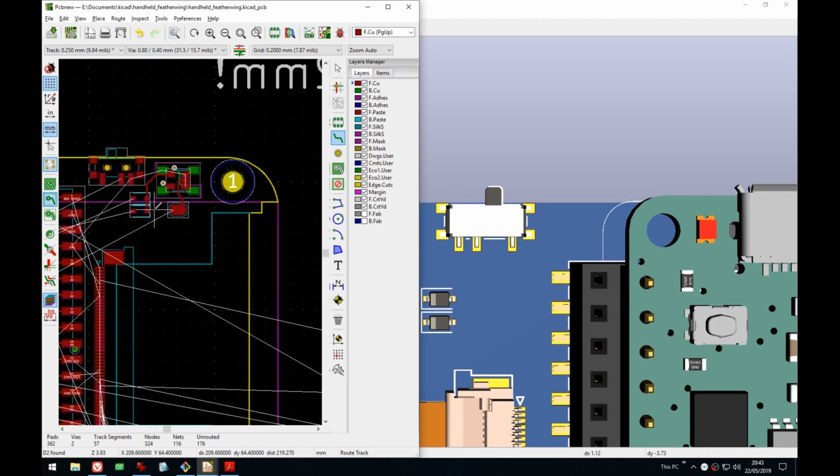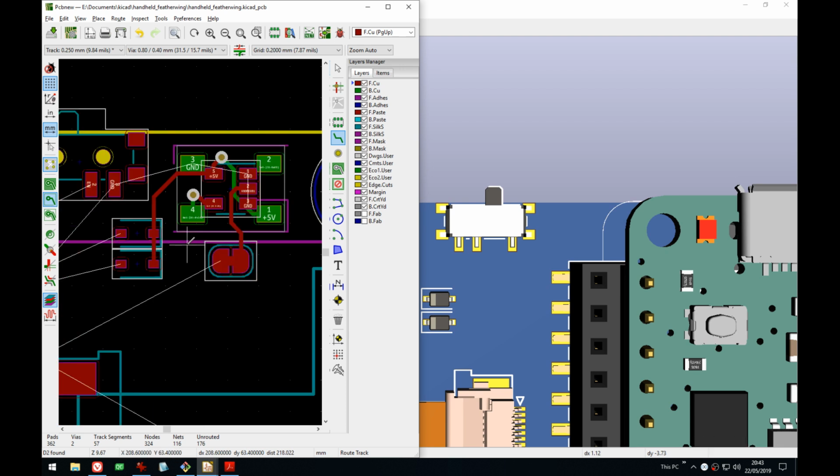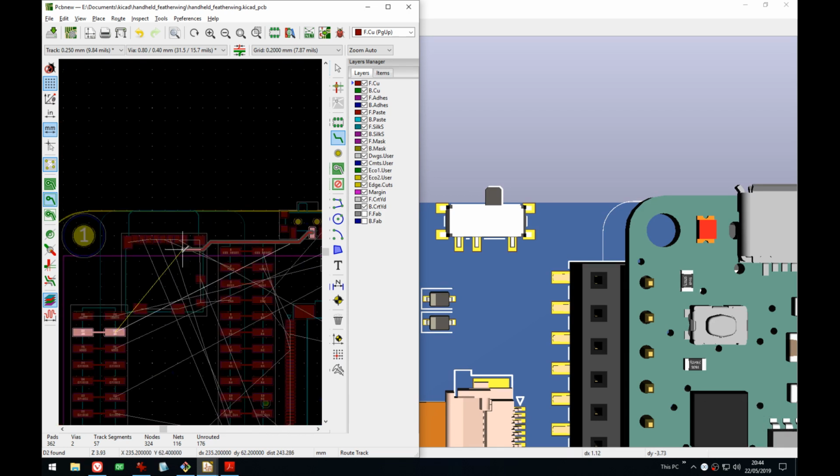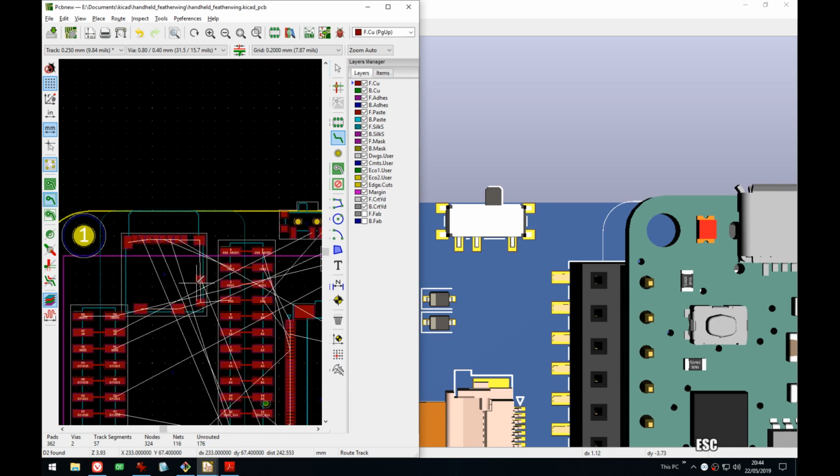The battery can do 4.2 volts, I think, when it's full, and then it goes down to like 3.6. And that's apparently good enough for the NeoPixel. So this is lifted from another Featherwing, where Adafruit also did this, and seems to work for them. So we do similar here. So you can still run the NeoPixel from the battery as well. So we have the enable here, and that's again all the way like here.